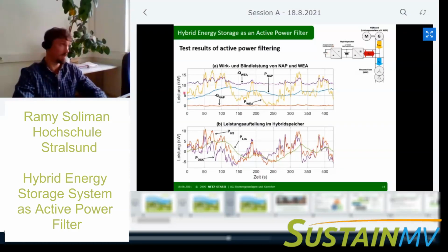The yellow curve is the active power of the generator. This is basically the original power flow I measured from our wind power plant, just scaled down by a factor of 6. The purple curve is the reactive power, which is needed to magnetize the generator. The blue curve is the active power we are providing to the grid, and the red curve is the reactive power from the grid.